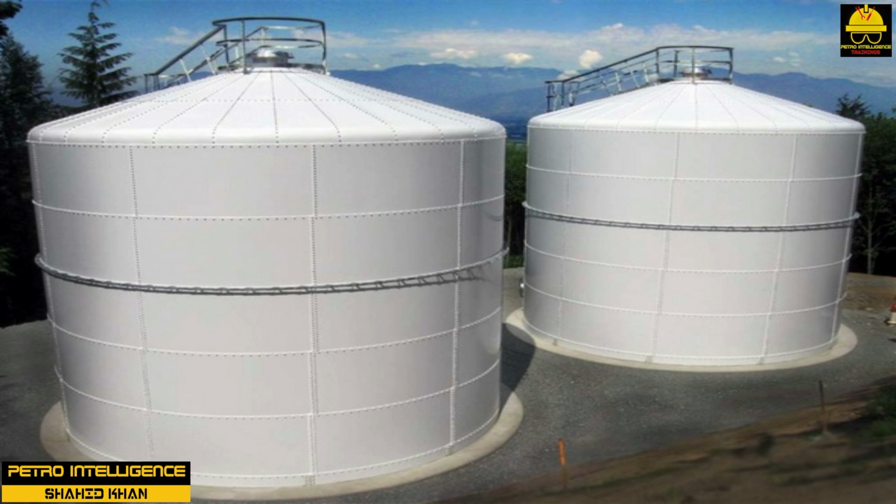of water vacuum. The welded joint where the roof joins the shell is purposely made weaker than other joints so that it will burst and relieve pressure without spilling the tank contents. This design helps confine the fluid should a fire or explosion occur inside a tank.